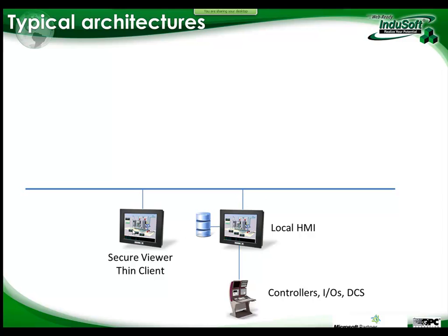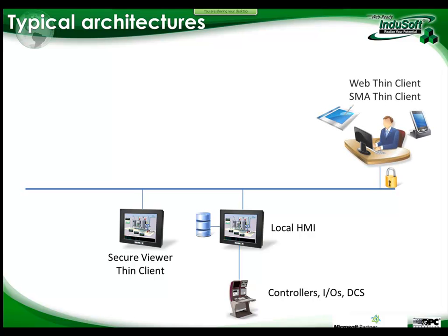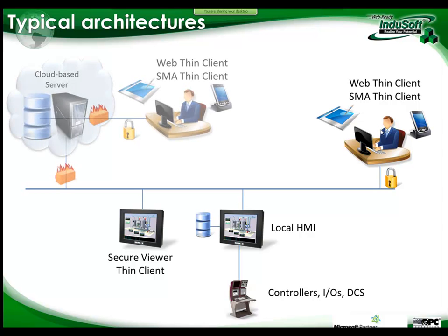This secure viewer will not be talking to my controllers, to my PLC, not even talking directly to the database, but actually talking to my local HMI that is acting as a server. Okay, and that server can also serve that data on my intranet to web thin clients. So you have someone in the management room, and they can open the browser and see the screens, see reports, see trending information, or get some specific information using our mobile access thin client solutions, again based on HTML5.